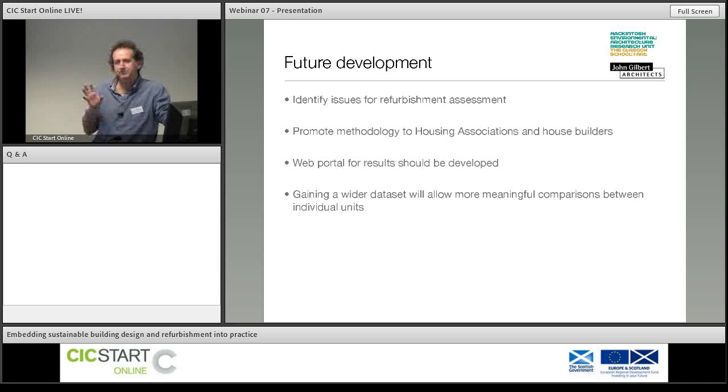And some of those things are just determined by the nature of the house. It has a particular volume, it has particular equipment in it, particular sizes, windows, trickle vents, things like that. And so they're trying to operate it in a particular way. So there are implications, therefore, in terms of potential refurbishment. Could you change the nature of the background ventilation? Why was there a draft from that mechanical system? Is the vent just in the wrong place? Is it running too quickly? Is there some change there?